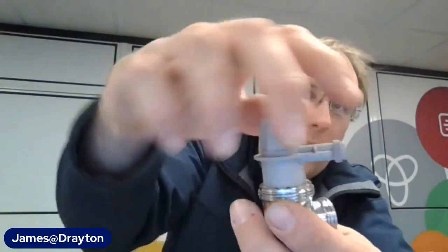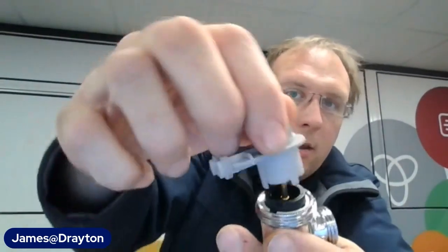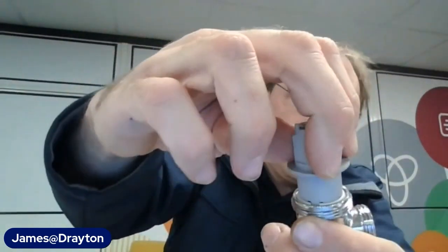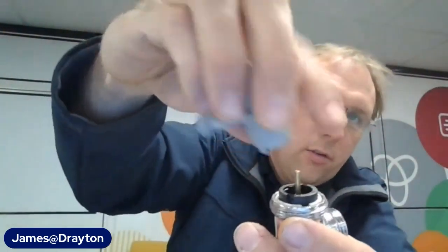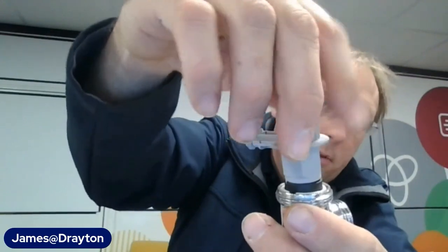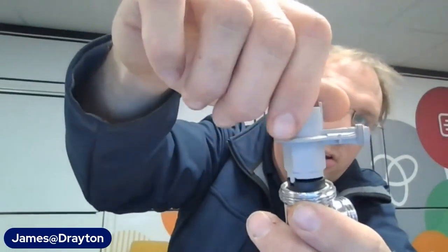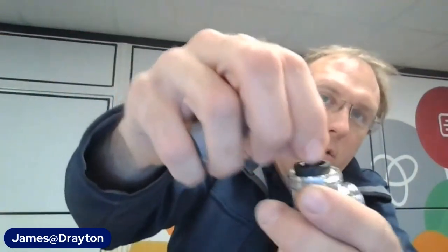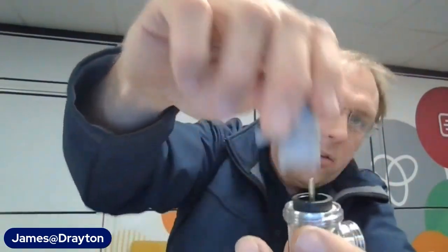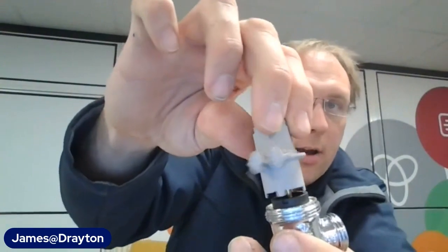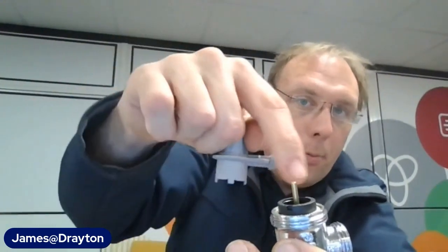Now, as long as that clamp ring was in and tight before you did it, if you turn it 180 degrees, it takes the load off of the insert, so it allows the insert to turn, and so you can turn it to one of those 6 positions, but it's not going to risk blowing out. So when you're turning this insert, you want to be turning it in a clockwise direction, so that if by turning the insert it picks up the clamp ring, it's only ever going to tighten it.